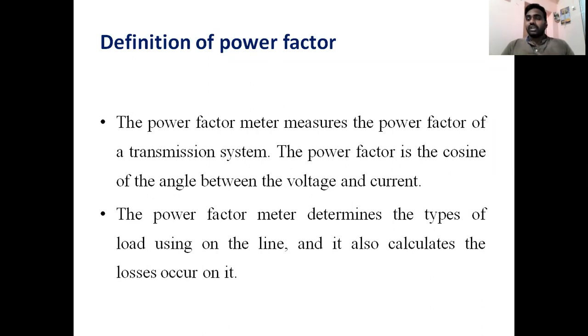Depending upon the range of power factor which we calculated from the transmission line, we can analyze what type of load it will be. Either it may be a resistive load or a highly inductive load. It may be an industrial load or a domestic load. Each individual load classification will have its own power factor rating. That means with the help of a power factor meter, when we measure the power factor at a particular transmission line, we can clearly determine the type of load we are using with respect to the line.